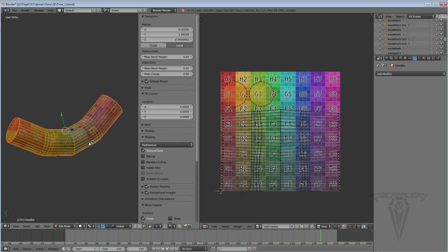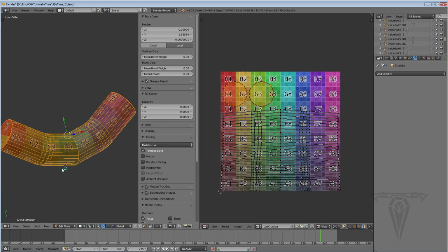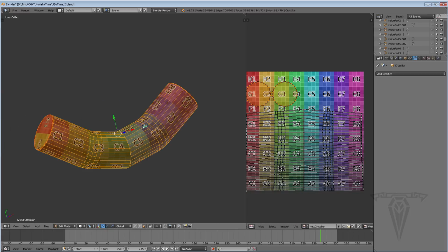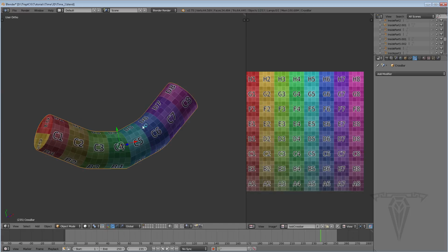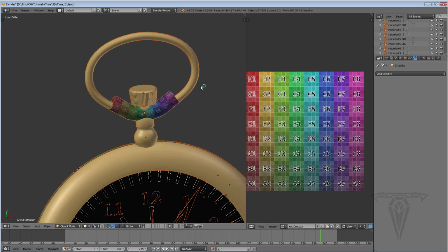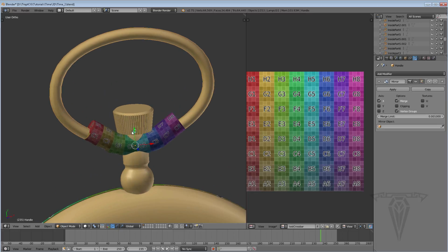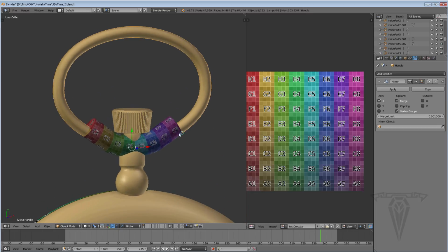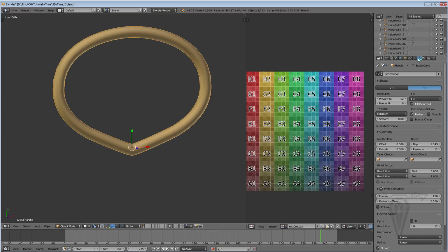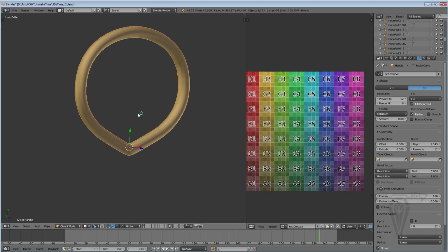All right, that's done. Let's go ahead and come out of edit mode. You just drag this over. I'm going to hit N to hide the properties, Tab to come out of edit mode, and Alt H to unhide all. Okay, so that's two surfaces done. Let's do this ring here. So this right now is a spline. Let me go Shift H to hide unselected. And as you can see here, not only does it have a mirror modifier on it, but it's also still a spline. So I need to convert it.